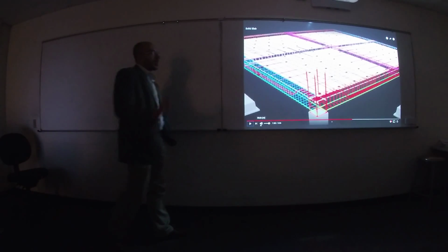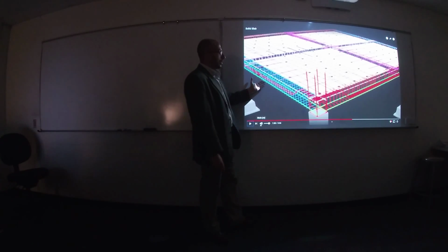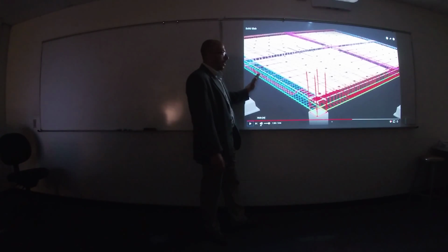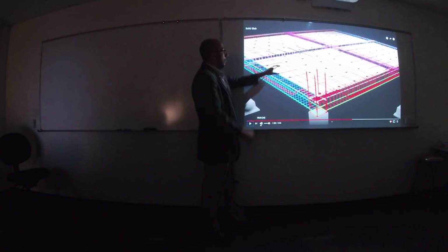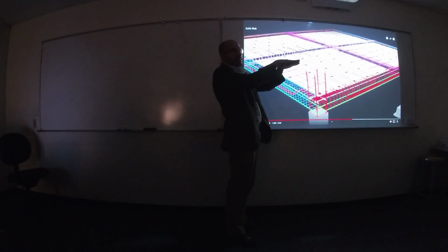So we understand what the steel for our beam is. We have bottom reinforcement, top reinforcement, and stirrups. Right? Mainly the bottom reinforcement is the main reinforcement, and the top is just to hang your stirrups. But for a slab, we have a mesh of steel reinforcement.